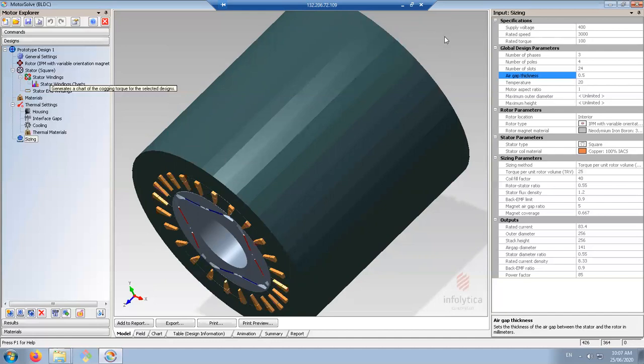That is usually used to decrease the leakage flux of the stator winding, to provide a better coupling between the stator and rotor, and also deal with thermal issues. However, for standard machines, it's not the case all the time.